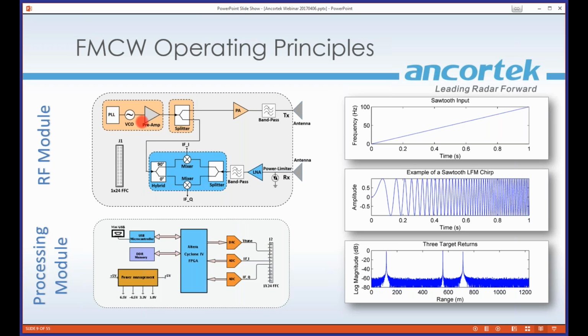That tuning voltage will set the PLL and the VCO to whatever frequency you're running at. So for example, if you're doing FSK or FMCW and you're doing a sawtooth, you'd start out at 0 or some low value, and you would ramp up. So that's what that V-tune looks like. And you can ignore the numbers here. This is all just representative. But essentially, you're making that voltage ramp. What that does is the output of the VCO then looks like this.